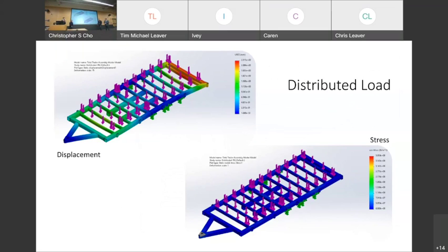So we could run with an option like that. We do have the ability and the space to do that type of option within the design of the tongue. When we ran our analysis on the forces, we didn't see any stress concentrations around the plane. So our initial design was just kept as is, since we didn't see any problems or any sort of red flags.